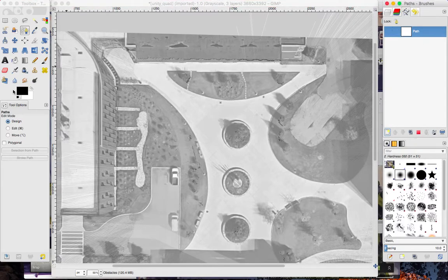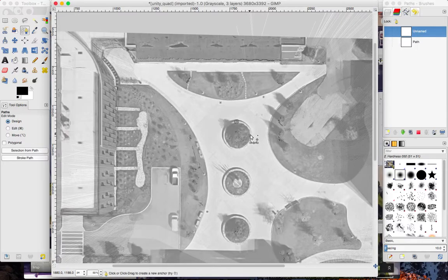And we're basically going to draw in all of our curbs right now. There's a couple different methods to do this, but basically it's a polygon tool. So just click points around the curb edges, and I believe Control-click or Command-click, depending on what computer you're using, to close the loop. Then once we have that, if you hit the edit button over here, under the paths area, you can drag this out and kind of start to form a circle.